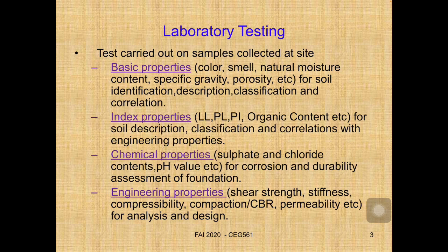But for cohesive soil, you have to proceed with sedimentation tests like the hydrometer, and then proceed with the liquid limit test and plastic limit test, because you need to find out the plasticity index, because plasticity index is liquid limit minus plastic limit.